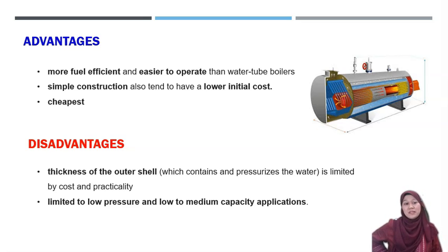And the disadvantage is that they have thick walls because they have to store lots of water and also the steam produced, and they are limited to low pressure. So it cannot generate power for the steam turbine. So the fire tube is more for industry application.